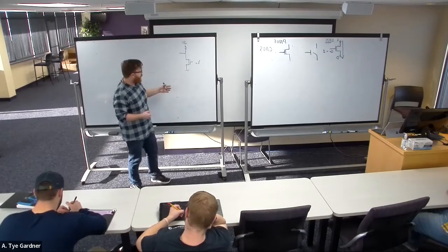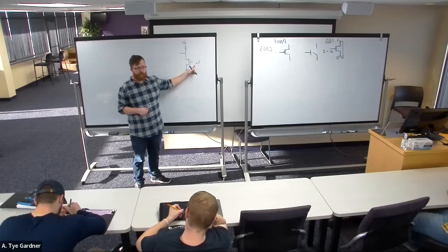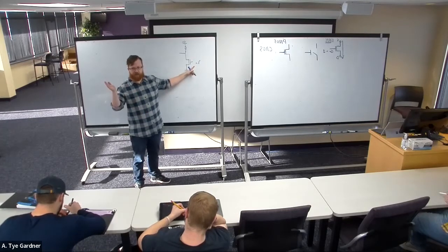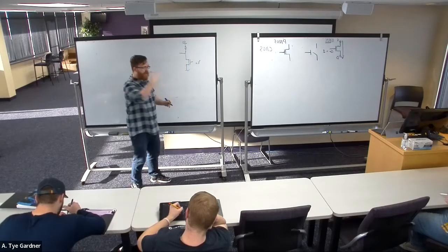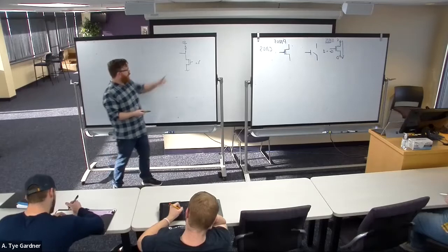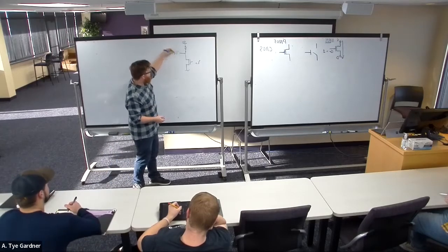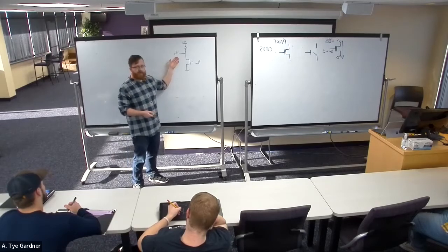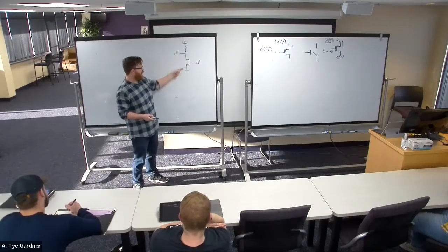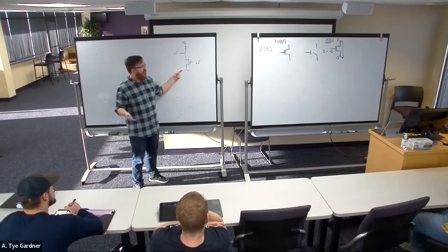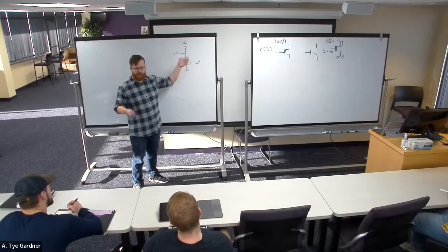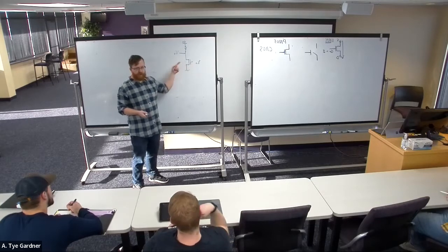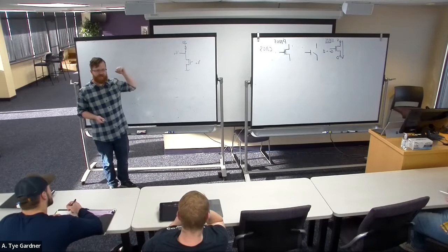And what happens is, if I put a 1 on this switch, it closes, right? You imagine this is the plate and you put a 1 and it pushes down and now it's a complete switch. The current can flow. That means this node, which I'm going to call V out, the voltage output, is ground, right? Because if the switch is closed, this is connected directly to ground, 0 volts. If I put a 0 here, the switch is open, there's no path to ground, the resistor pulls it up, and I get a 1, right? So a 1 makes a 0, a 0 makes a 1. I built an inverter, right?